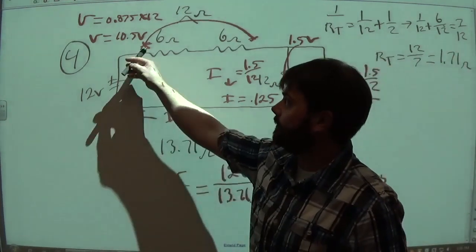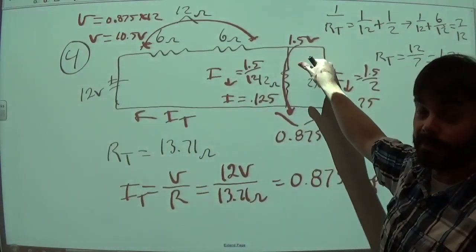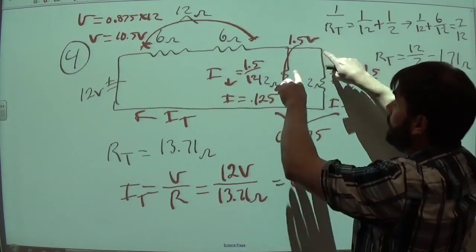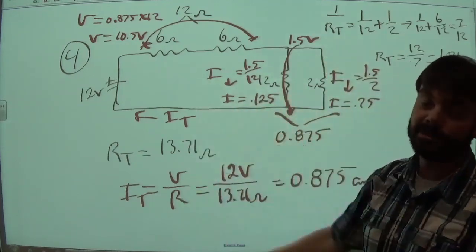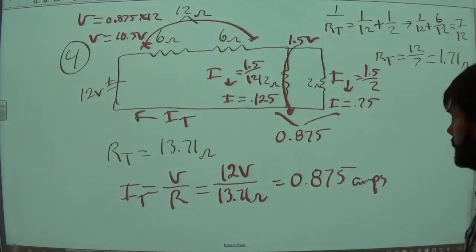If you had 5 gallons per minute flowing through here, if you break that 5 gallons per minute, if this was water in a hose or whatever, into these two, coming out the other side still has to be 5 gallons per minute, or in this situation, the amperage that we have total.